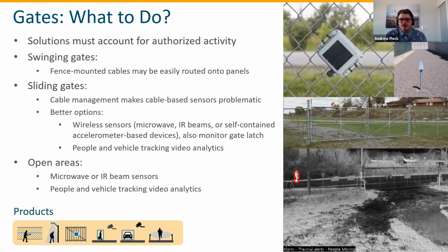The main reason we do that is the fence sensor cable can adjust and it can handle the open and bend of a swing gate. Normally as well, a swing gate is not as frequently used, so the movement on the cable is a little easier. But sliding gates tend to become where we have the issue. There are many different issues in them because affixing fence cable to the fence is one of the worst solutions that we can do on a sliding gate.